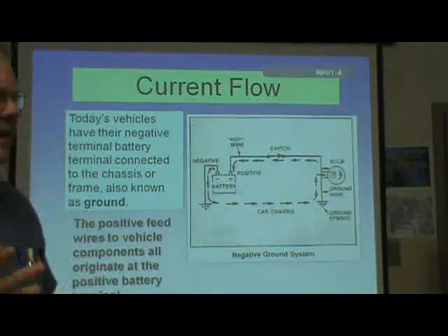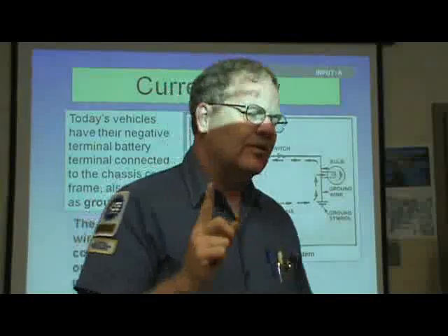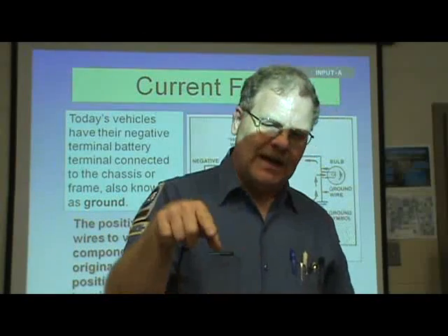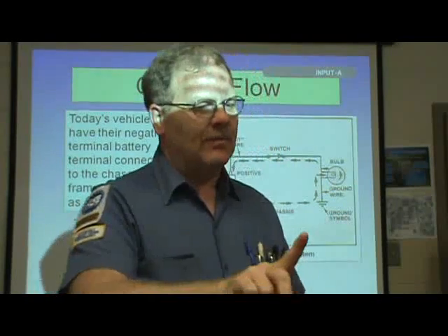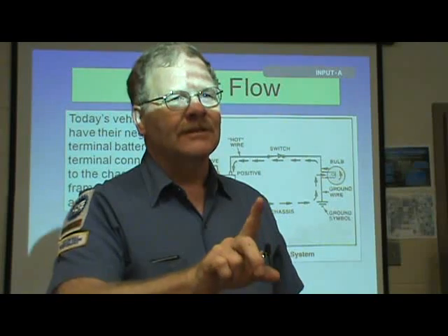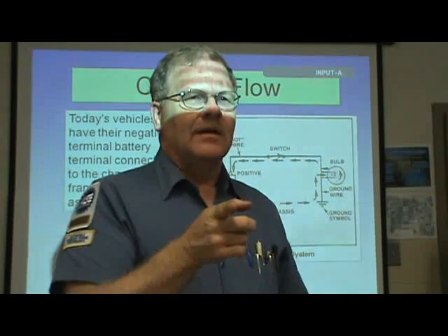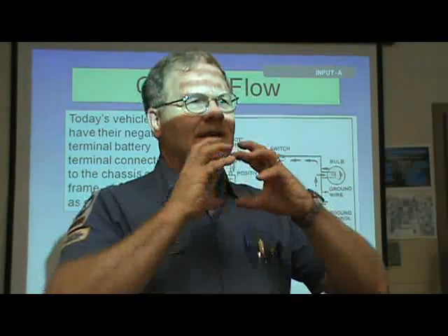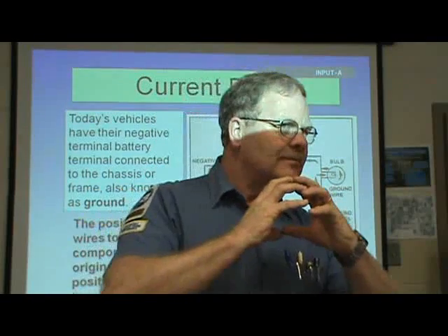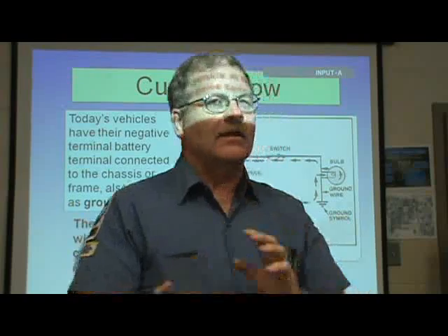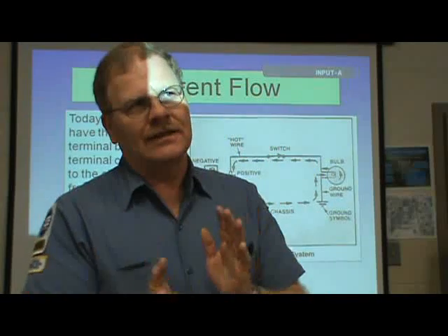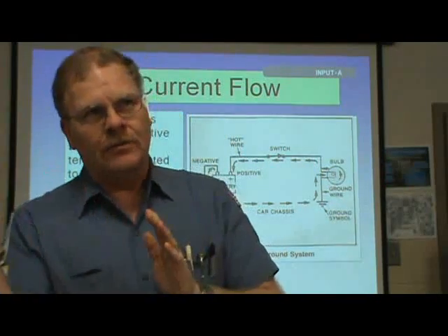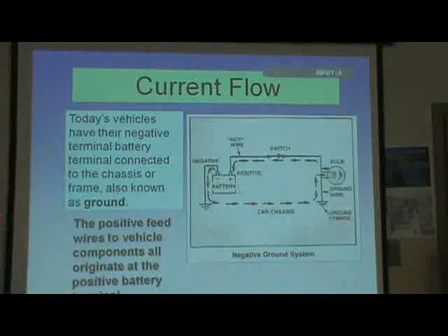But have you noticed that a lot of times your ground terminal leaving your battery, your ground goes directly to a bolt on the starter? You seen that? One of the bolts that goes to the starter will have that ground on it, because the starter needs a ton of ground. I mean, it needs a lot. So they're going to make a good solid ground connection to the starter directly from the battery, and whenever they do that, they're doing it for a really good reason.